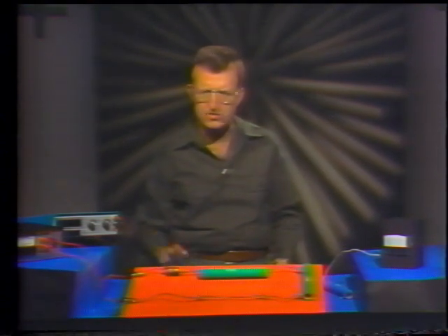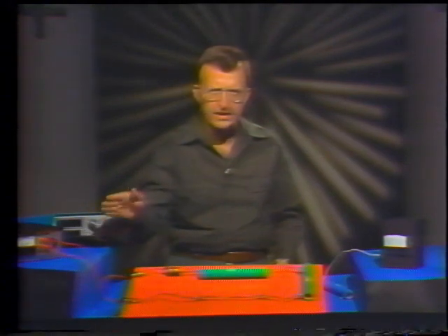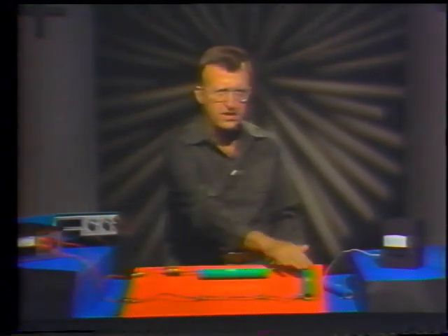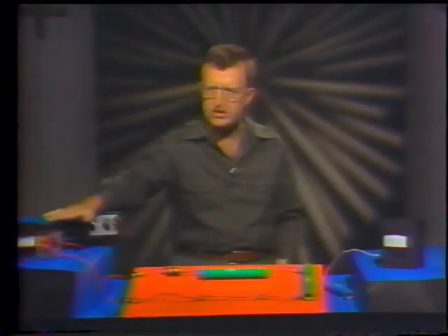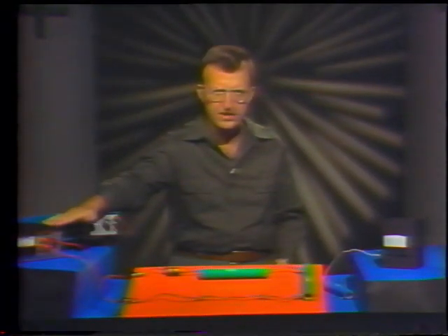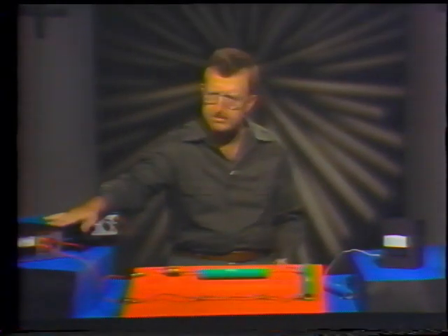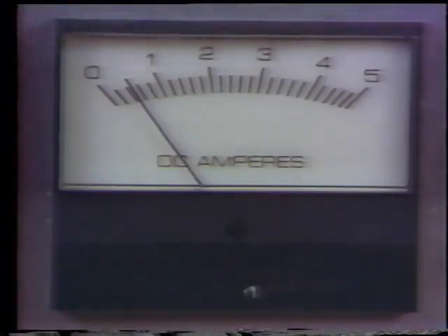With one 10-ohm resistor, the current in this circuit was 1/2 an amp. Now we have two 5-ohm resistors. The source voltage is still 5 volts, and according to Ohm's law, which relates current, voltage, and resistance, if voltage and resistance don't change, current won't change either. If the total resistance in the circuit doesn't change when we replace one 10-ohm resistor with two 5-ohm resistors, then the current in this circuit should still be 1/2 an amp, and it is.